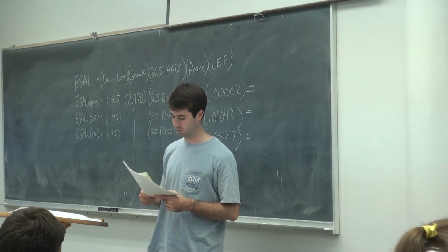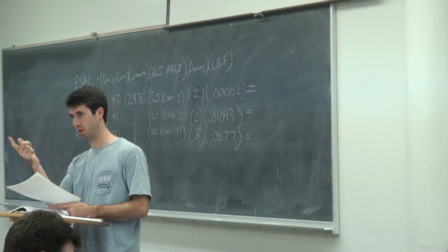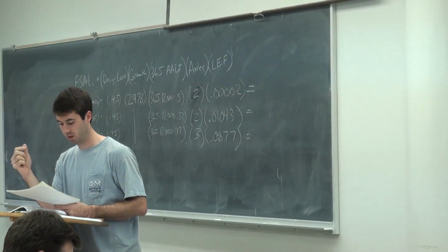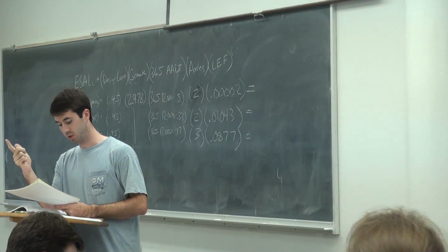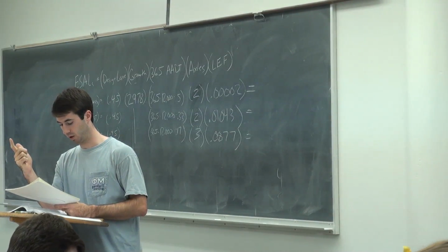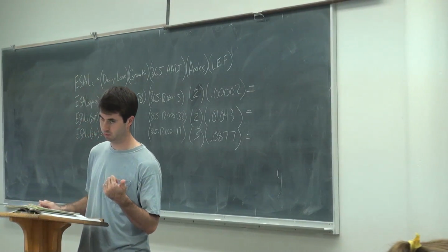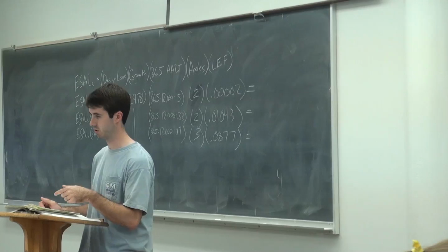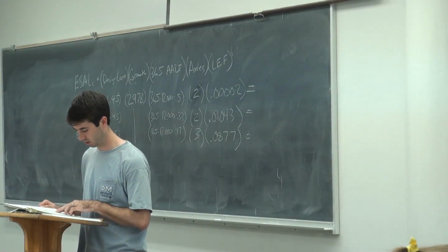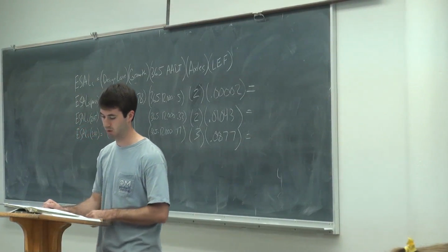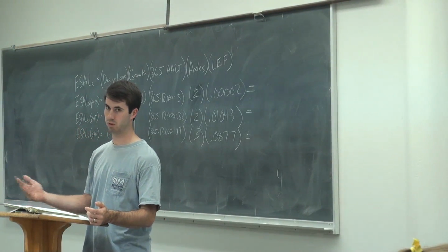Phase diagram. And all this terminology, these little symbols and stuff. V basically always means volume. M always means mass. G always means specific gravity. P always means percent. Now, the subscripts, if you're talking about aggregate, S means stone. So if you see G, S, specific gravity stone, it'll have some sort of other qualifier. You got B, A, or E. So you got GSB, GSA, GSE, specific gravity stone, bulk, apparent, effective.